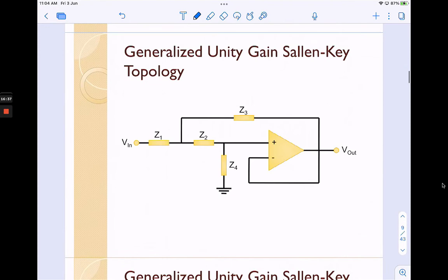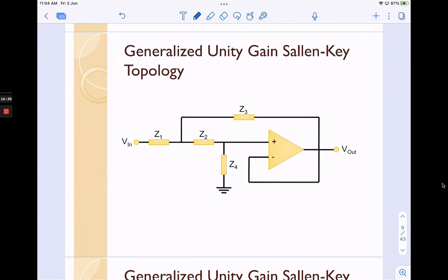actually this Sallen-Key is one of the most widely known and popular second order filter designs, because it only requires one single op amp to have gain control of the second order filter. A second order filter has a steeper transition between the pass band and the stop band.